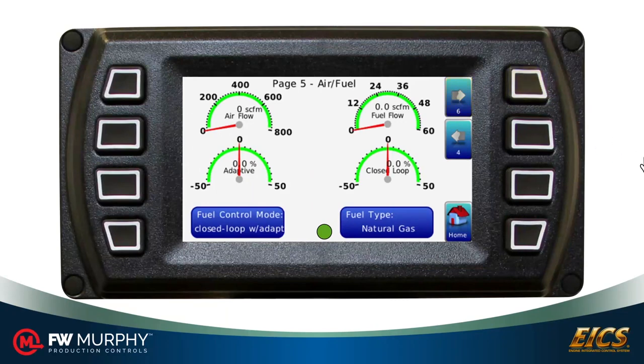Air-fuel ratio information is shown on page 5. This shows the airflow going into the engine shown in standard cubic feet per minute. Fuel flow going into the engine shown in standard cubic feet per minute. The adaptive percentage based on the control strategy. Closed loop percentage based on the control strategy. At the bottom, we see the fuel control mode that may be set with open loop, or closed loop with adaptive. We also have the fuel type, which can be natural gas or propane.